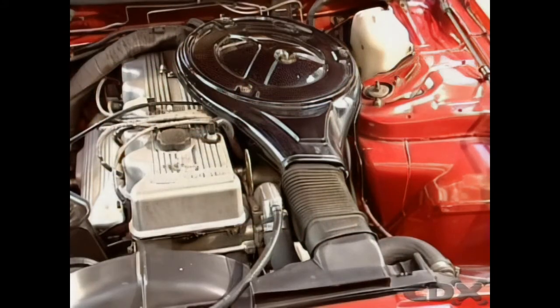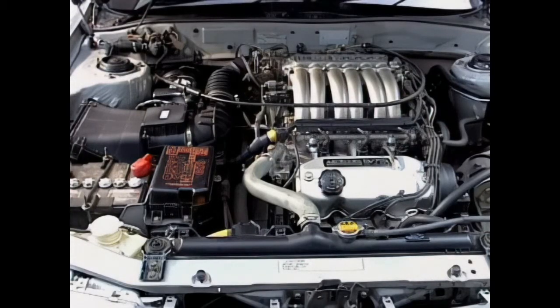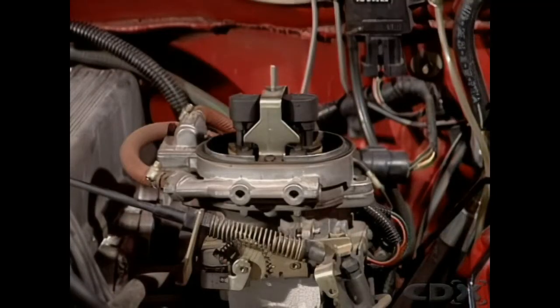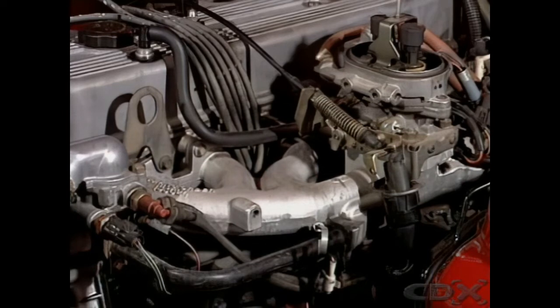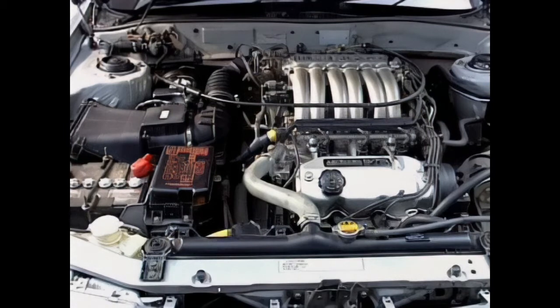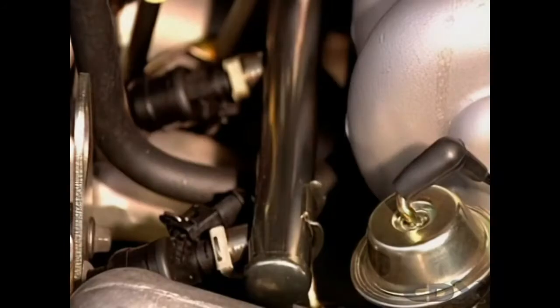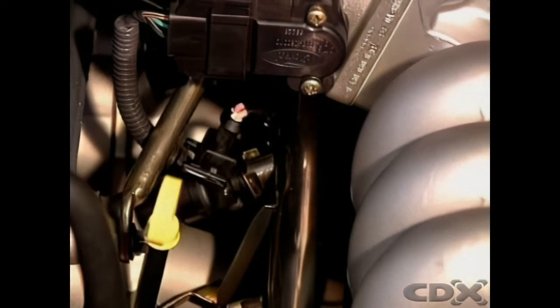There are two basic electronic fuel injection systems, single-point and multi-point. In the single-point system, the intake manifold carries an air-fuel mixture. Fuel is sprayed into the top centre of the intake manifold. This manifold is similar to that on a carburetted system. In a multi-point system, the intake manifold carries air only. Multi-point injection has a fuel injector in each inlet port going to each cylinder. Gasoline is sprayed into each port in front of the intake valve.